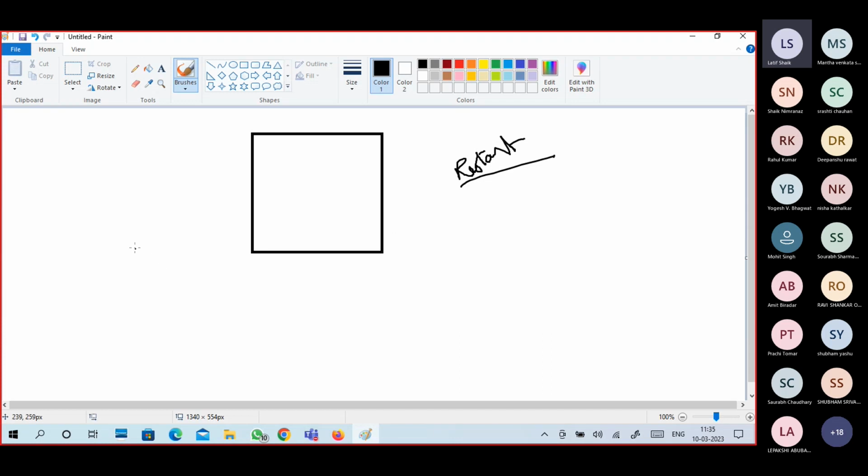One of the reasons is your processor. There is heat sink paste. Maybe someone disturbed this heat sink paste. Sometimes, for cleaning purposes, you clean this heat sink paste. Maybe the heat sink is not sitting properly, or maybe the heat sink got a lot of dust.